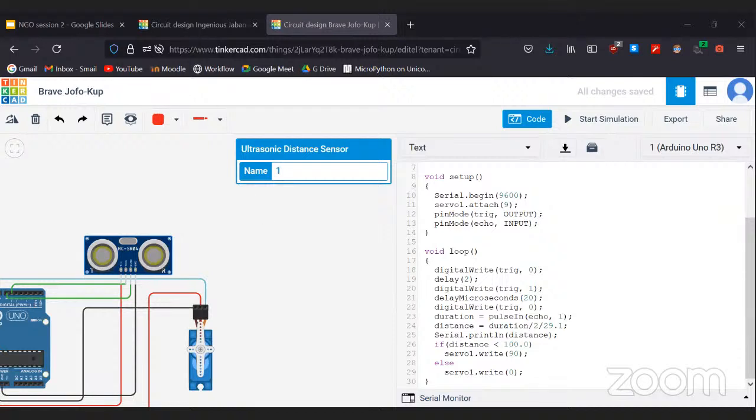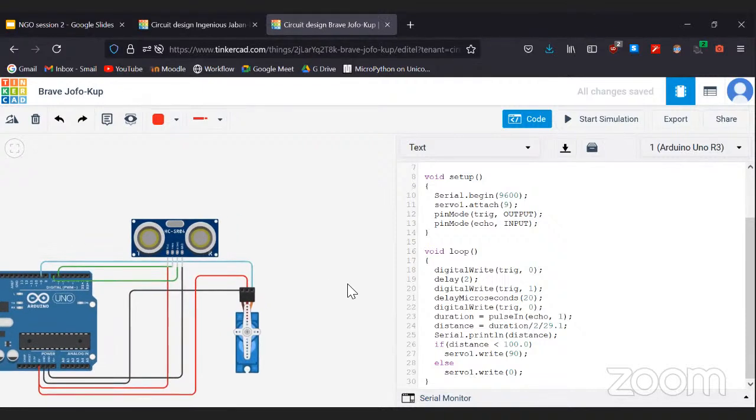As you can see, this opens up a huge range of possibilities for you. Now using Arduino, you have a motor that can actually change the position of a physical object when the sensors receive a certain value. For example, you learned about the LDR and the servo motor now. So you can use those two to open the shades of your room if your room becomes dark, and close the curtains when there is already light. Or you could let it turn the windows open when the room becomes hot using the temperature sensor.